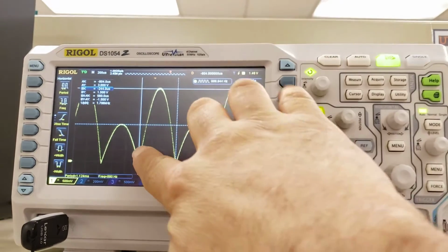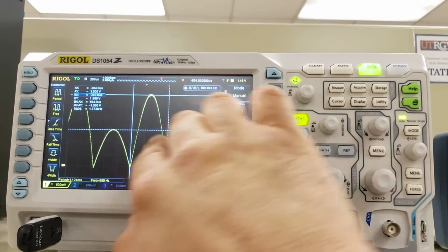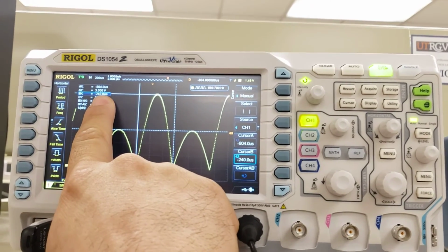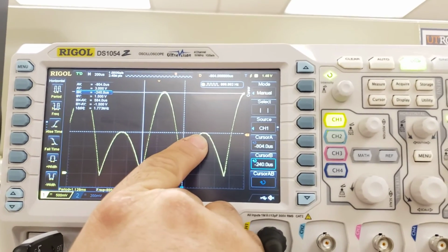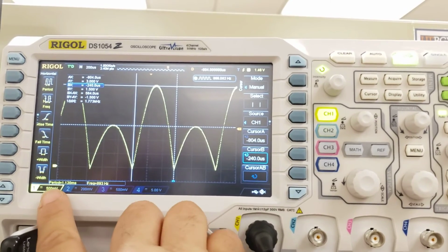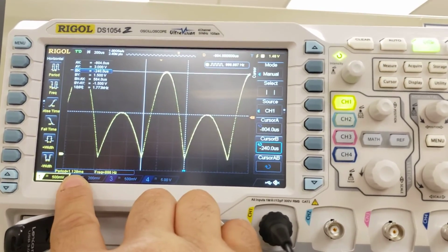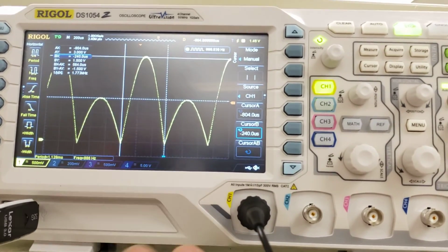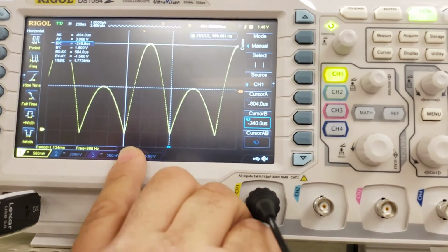Here you can see that we are achieving the waveform that we're required with the first waveform amplitude of 3 volts, the second section of 1.5 volts. Total duration here, our period, is 1.124. It fluctuates here, just the clock cycle on the microcontroller. Also a little bit of error here in the cables, not that bad.